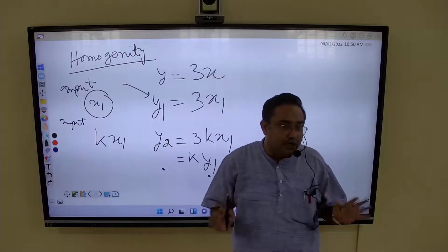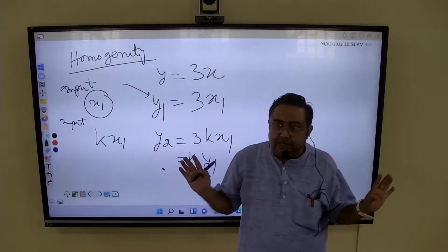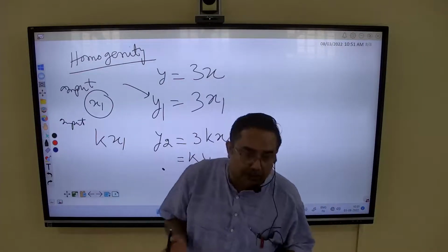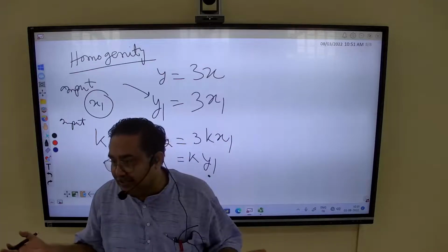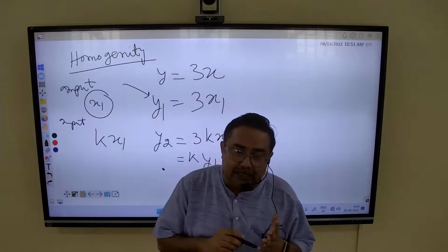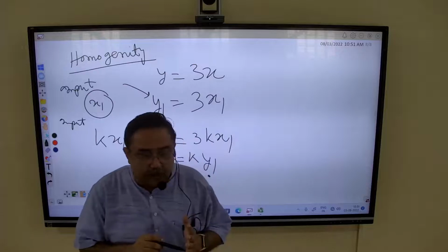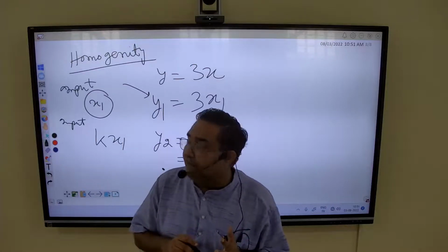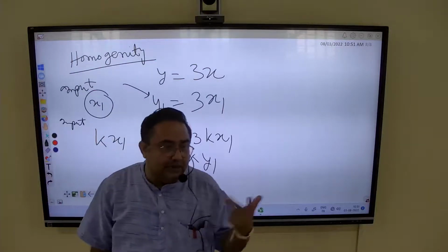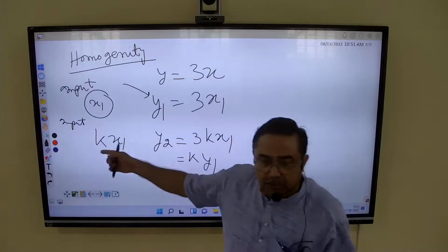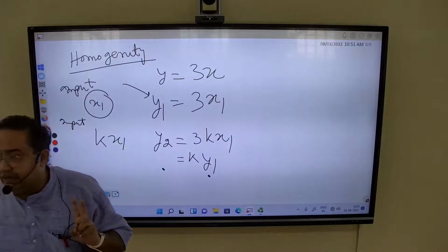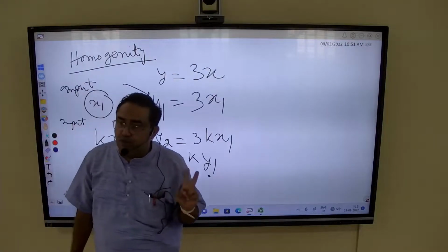Did you get my point or not? This is clear: how to identify mathematically whether the given system is linear or nonlinear. Practically it is also easy. First of all, identify what is your input and what is your output, and accordingly you must have an instrument to measure your input as well as output. For example, take this fan. I have already told you the input and output of this fan. Input is voltage and output is speed, in RPM. So which instrument do you require to measure these two quantities?